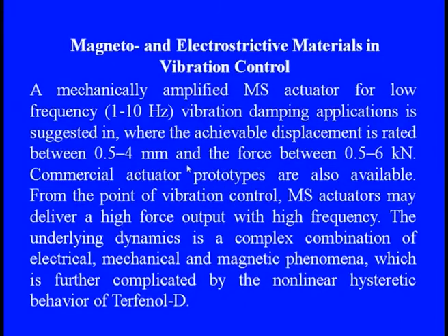So whether we go with electrical, mechanical or magnetic phenomena, we can use this MS actuator concept, but we need to understand it using the nonlinear hysteresis behavior of terfenol-D, because when there are loading or unloading conditions, there is a clear loss, and this loss is not linear.